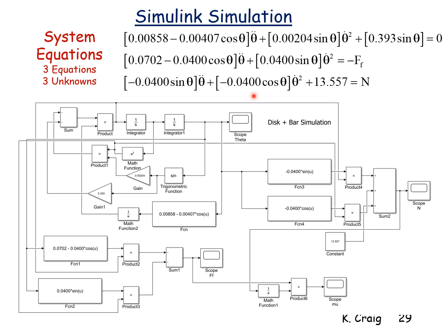I expect you to follow the rule of not including any numerical values in your Simulink diagram, except numerical values that are part of the equation themselves. We don't include parameter values in our Simulink diagram. We let the parameter values propagate into our simulation diagram from the MATLAB M file.